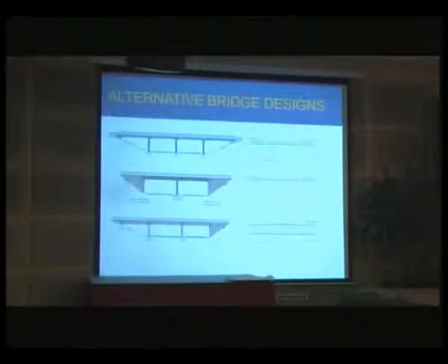Bridge 3 is, as you can see, 3-span. It's made of in situ voided slab. There's a bank seat at one end, and there's a cantilever abutment with wing walls at the other end. And there are intermediate supports which are made of columns and crossbeams. So those are the 3 alternative schemes that we came up with for this particular location.